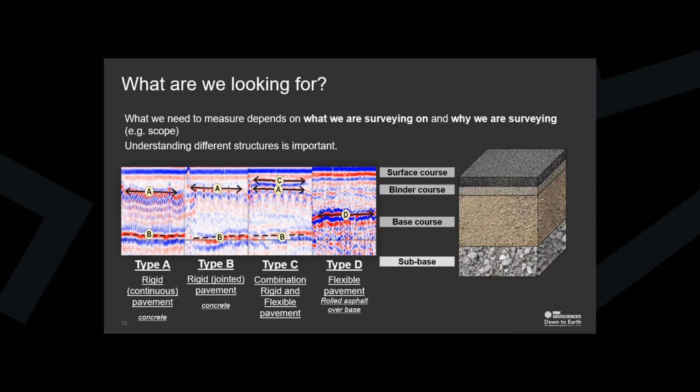And we're also looking for anomalous areas within the data, bright spots or dim spots, that can indicate voiding or delamination between pavement construction layers, or even moisture contamination within the road. And basically anything that we think the client might want to know about is something that we can pick in the data and put on the construction charts to give to the client as a deliverable. And as part of those construction charts, they're going to be cross-referenced within the report, where we'll give data examples of what we've seen and talk about generally what we think this anomaly might be.